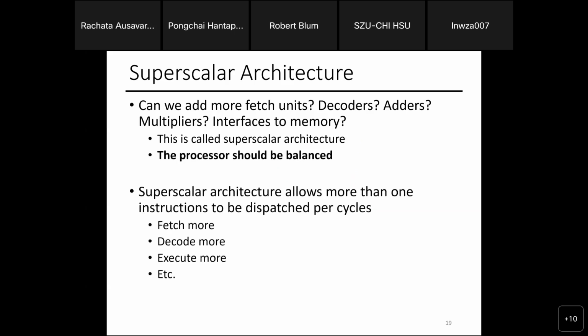So in traditional pipelining, you can finish only one instruction in a cycle, right? But with superscalar, internally, we are finishing a bunch of them in parallel. Still need to ensure write back happens in sequence, all right? But internally, your code has already gone to the future. It's just that at the end of the day, I report to the programmer later.